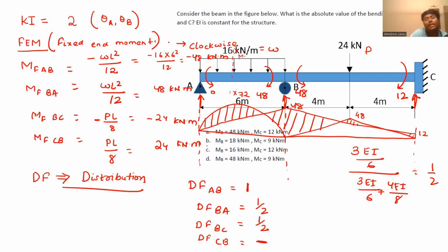After you write MXX here, then you shift to this side. You again consider this as some section XX or YY or ZZ as per your requirement. You again write the equation, and always take X from a specific point so that you won't fall into any problem. While calculating, you might make a mistake, so always fix the origin and take X from there only. Write the bending moment equation at every section and plot it. You will get the complete bending moment diagram and you did not superimpose there.